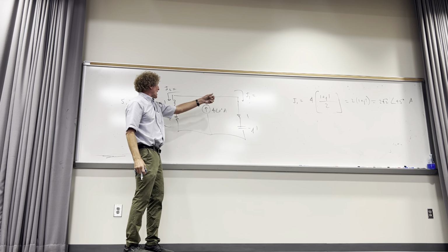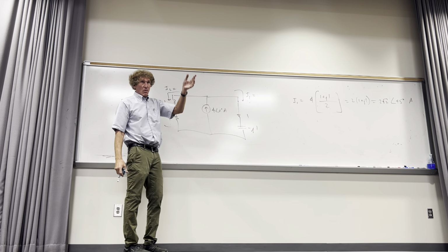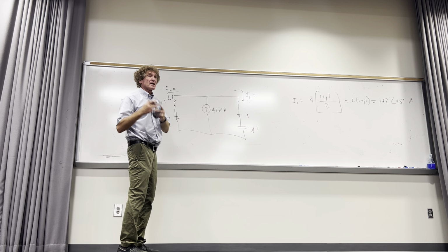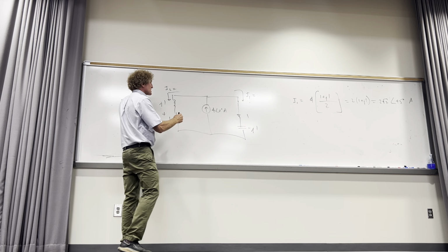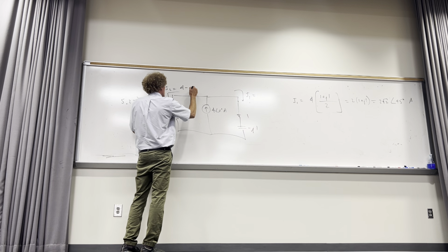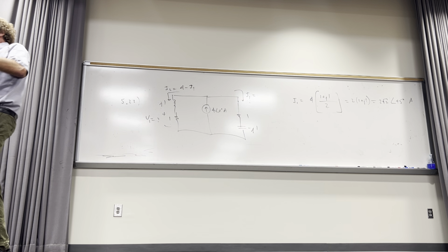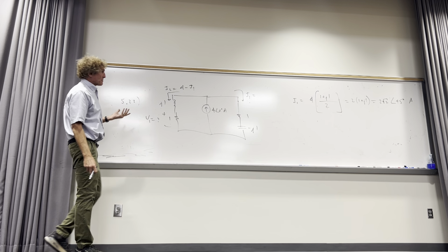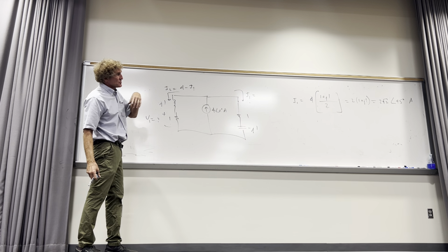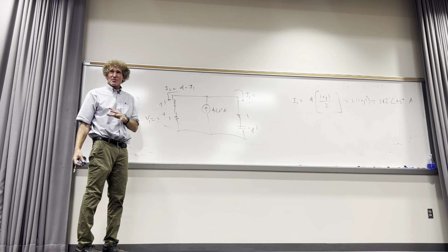Doesn't 4 amps equal I1 plus I2? How many see that? Instead of doing current division again, which we could, just say that I2 is 4 minus I1, and I'll just put minus I1 so you can see. Y'all agree with that? Let me see that. These are questions that I kind of ask, and I assume you can see this. All right, now if I have that current, what would that be? Well, it's 4 minus 2 square root of 2 at 45 degrees. You can do it on your calculators. Do you agree with this class?